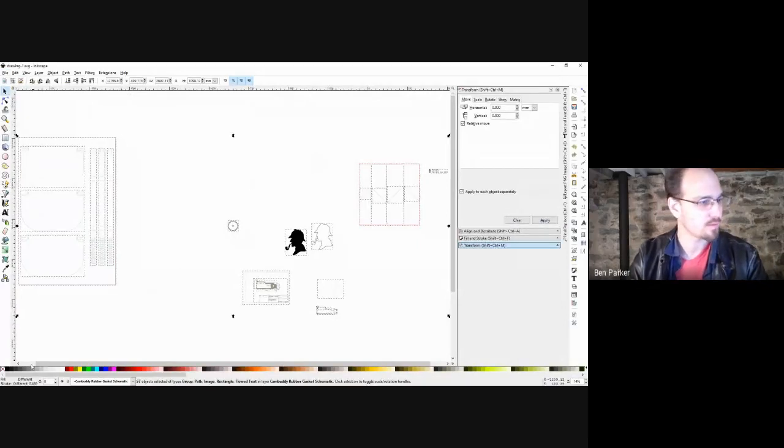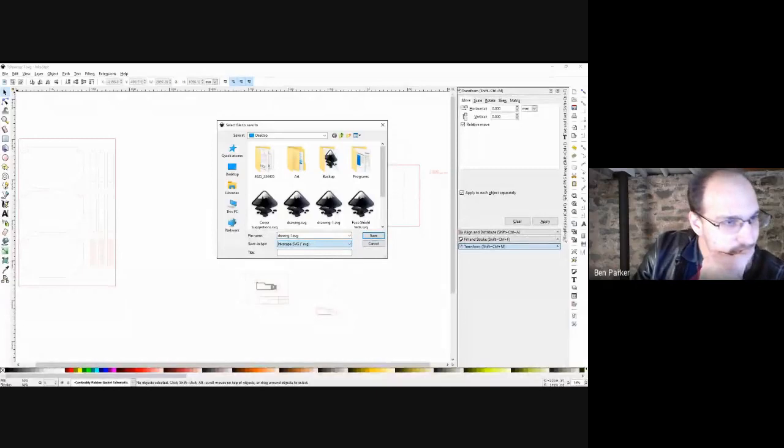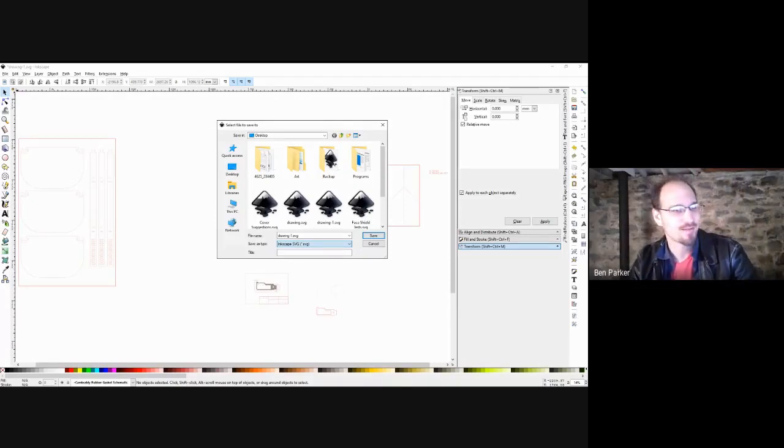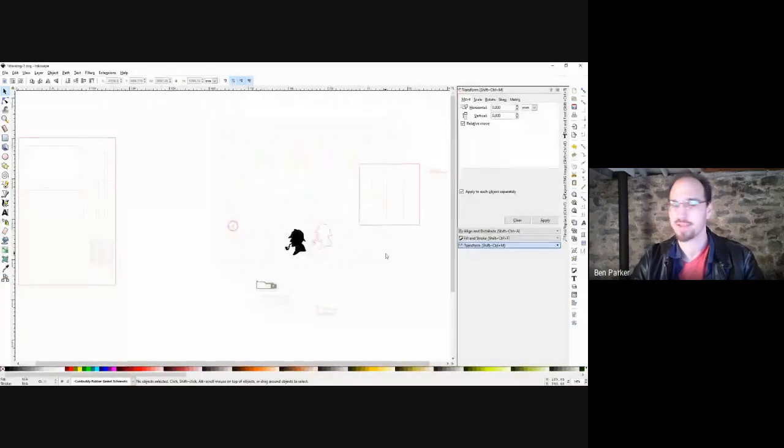So I'll do that. I'll remove all fill. Give it a red border, like the thing said. Save as Openscad cookie cutter file. That's pretty cool. So that'll open as a .scad. So in the free program Openscad, you could then export that as an STL for the 3D printer. And so that's a kind of a crash course in how to install an extension and use it.